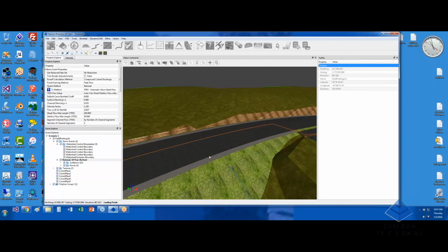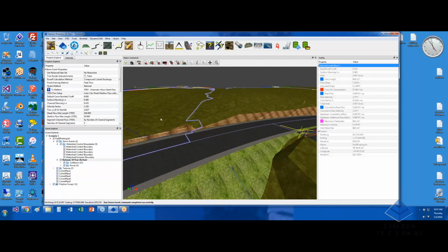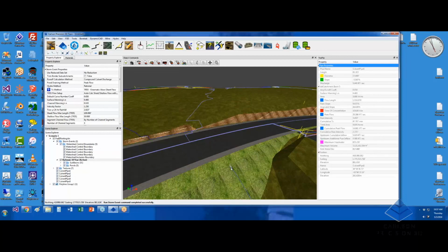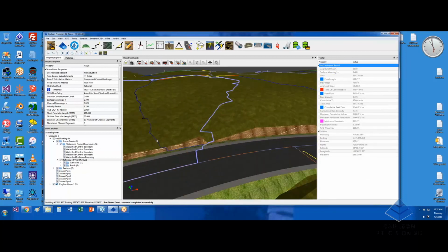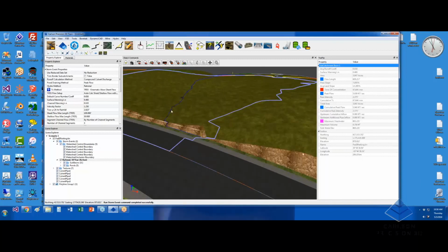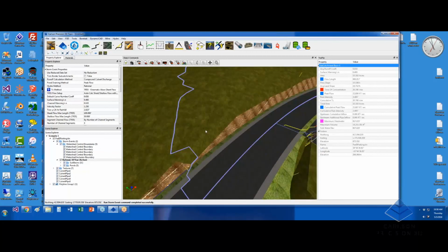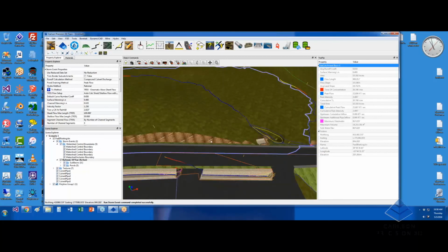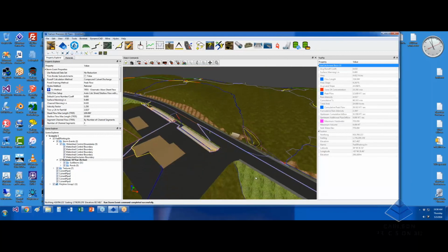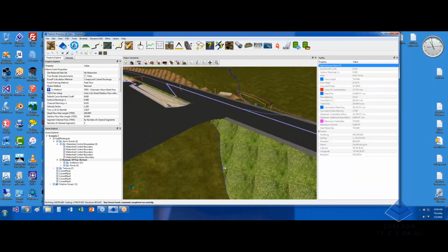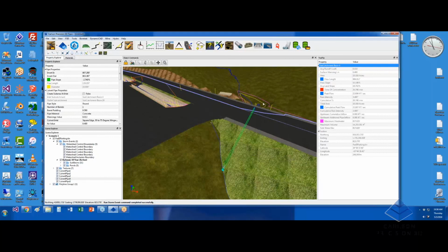And so what you're going to see here is that not only did the pipe get smaller, but now we have a new sub area. So from this point, this is the subbasin that will contribute water to that point. And we can also see that it's reduced the amount of water that's going to come over into this pipe, where I think before we had a 21-inch pipe, but the headwater was much higher. Now we're down to an 18, and we still have a nice, decent headwater value here.